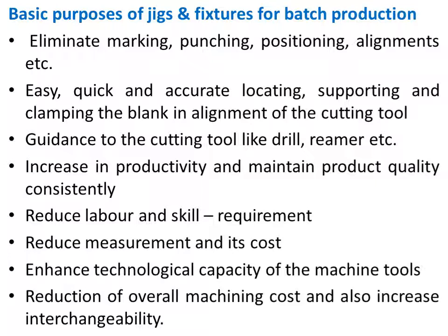Then enhance technological capacity of the machine tool. Even if the machine is not very precise and accurate, and there can be some kind of misalignment, that is not going to affect the component, because the drilling is taking place considering the jig as the main guidance for the drill. So even if there is a small inaccuracy on the machine, it is not going to affect the accuracy on the component.